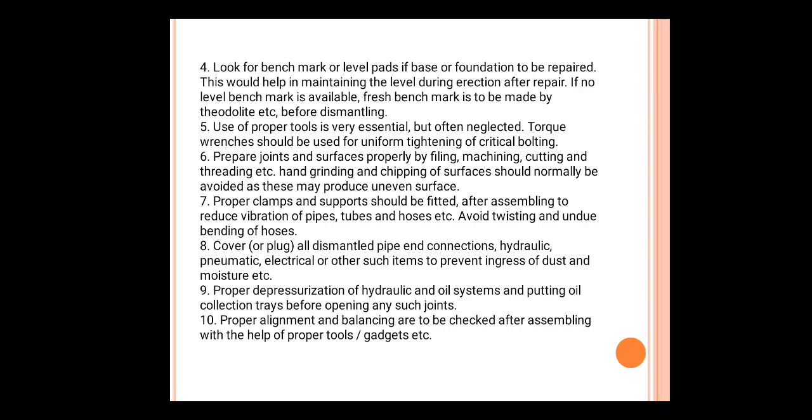Fifth, using proper tools is very essential but often neglected; torque wrenches should be used for uniform tightening of critical boltings.